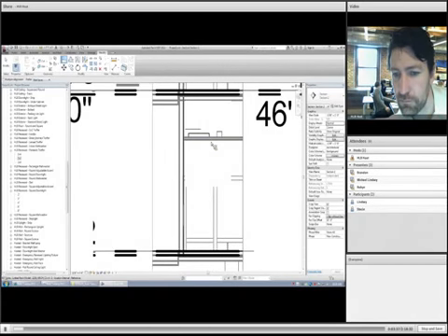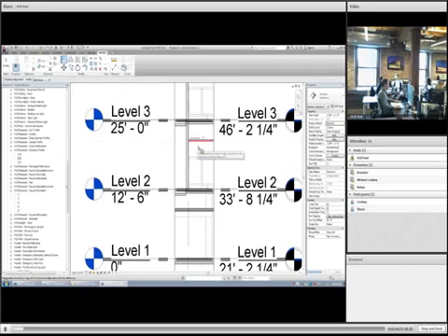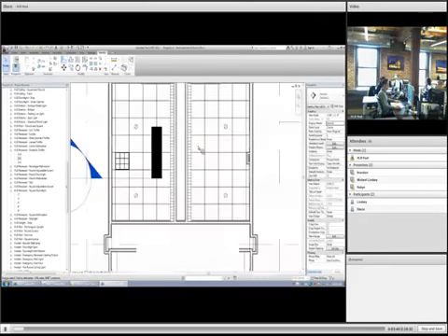You were placed on a work plane, right? That was free. It was not placed on anything. Because one of the things that I've noticed in the past is that if you do reference plane or level and you place it on that work plane, recessed fixtures come in upside down. Right. So you have to flip them. Yep. And can you do that in plan?